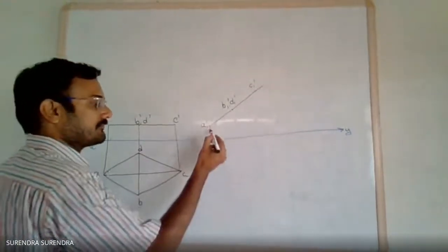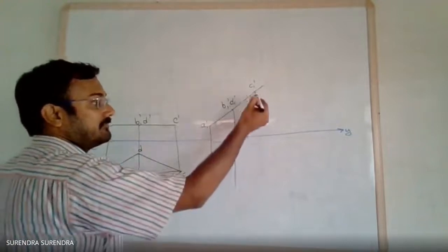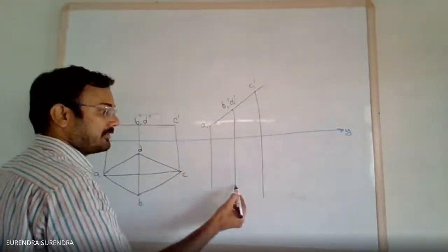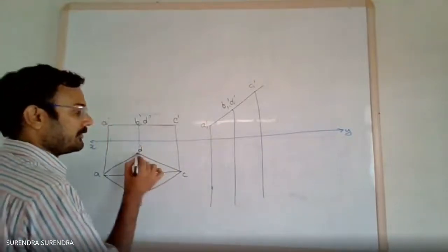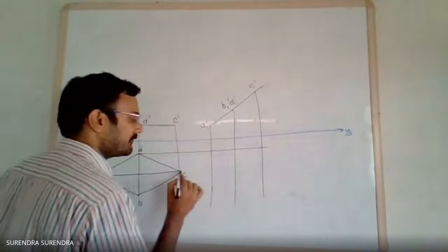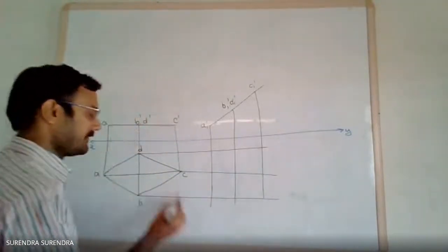Now draw the projections from the previous view to the top view and locus from the initial top view. Mark the respective intersection points.